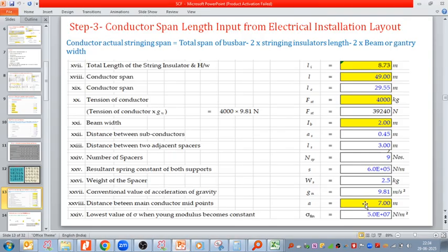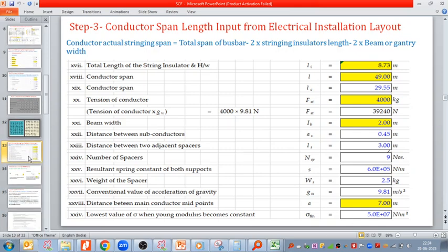This question may appear a bit silly, but this is really a gray area for me, and that is why I'm asking. The short circuit forces that we are referring to, on the pulling, the supporting end at which the tension will happen, is it independent of the phase on which the fault occurs, or is it meant to be a three-phase fault only? Yeah, three-phase fault.